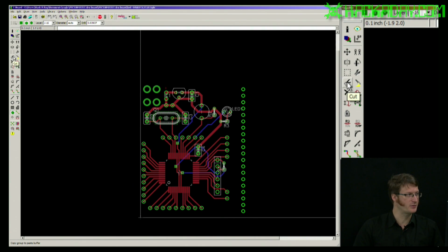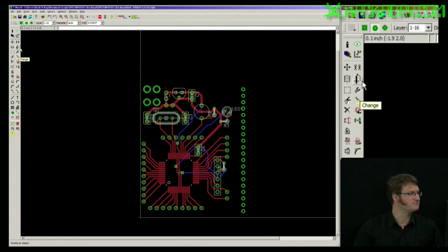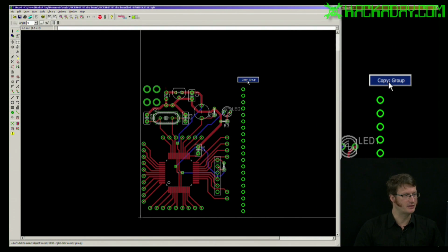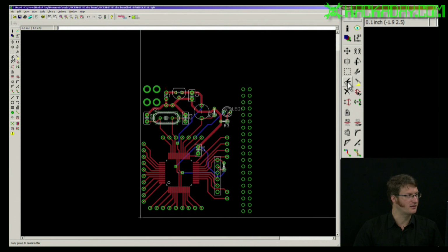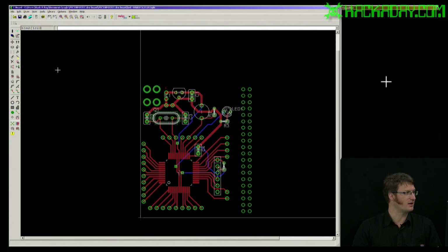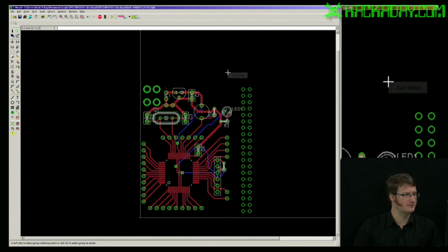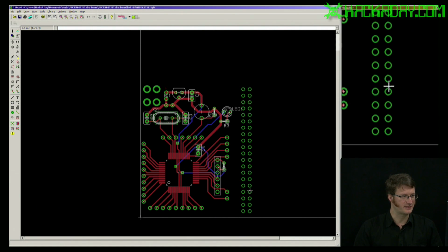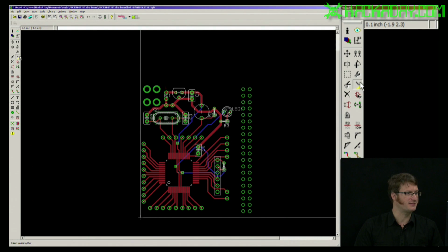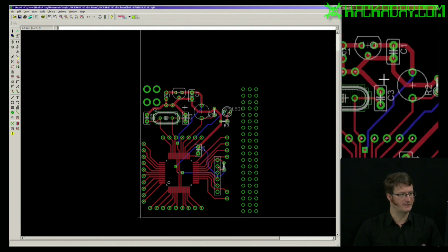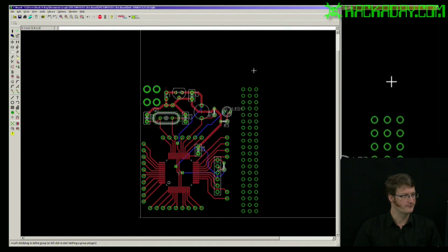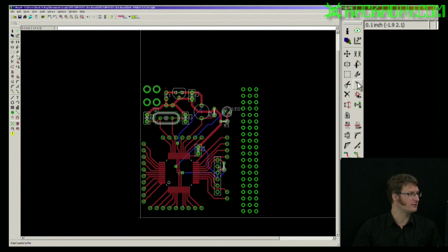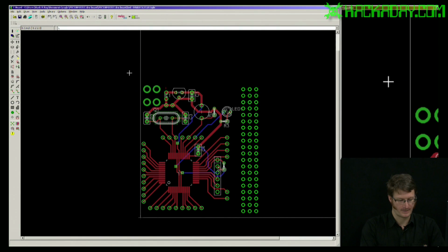It's strange. In this program we have, actually I could copy as well. I can right click and I can say copy group and do that. But sometimes you also want to cut and paste. Say you're cutting something from one layout to another. So I could do cut group, which actually doesn't cut it. It's weird. And then if I paste, I get another one. But this allows me to copy something from one schematic or one layout to another. But I'll just copy.